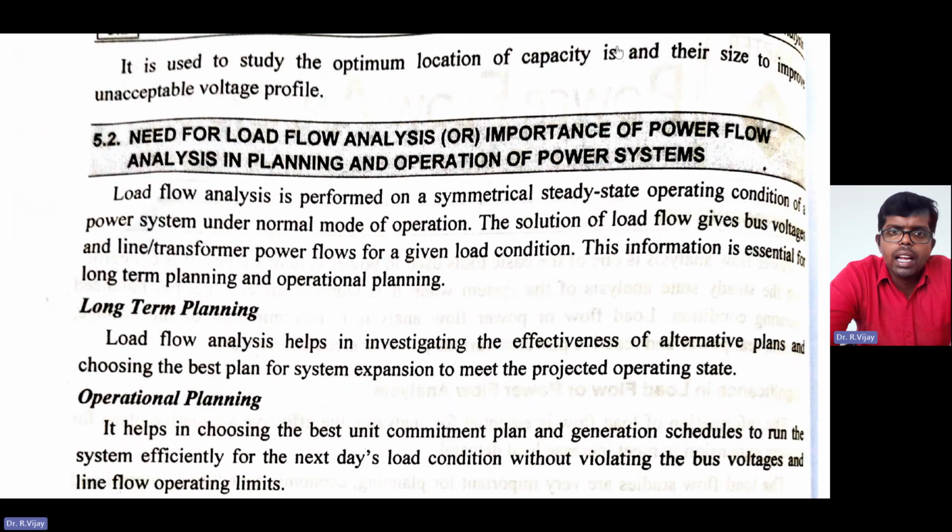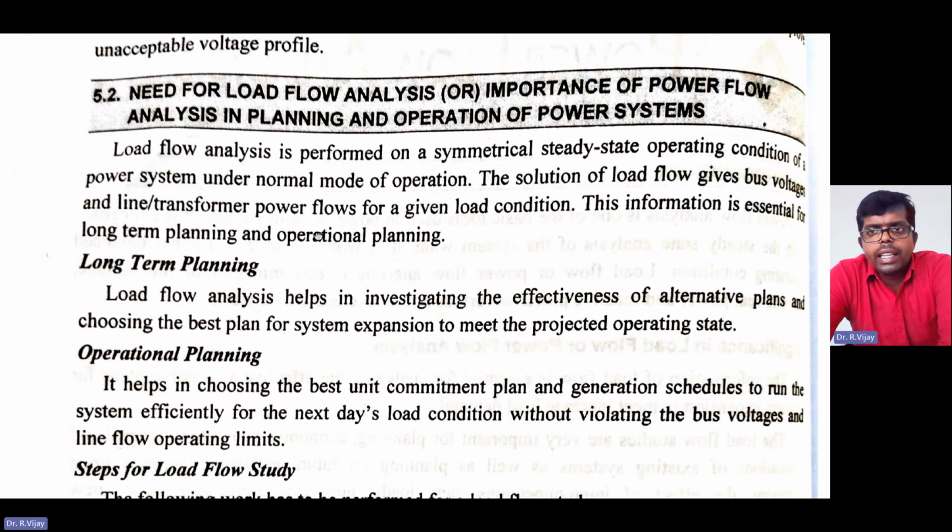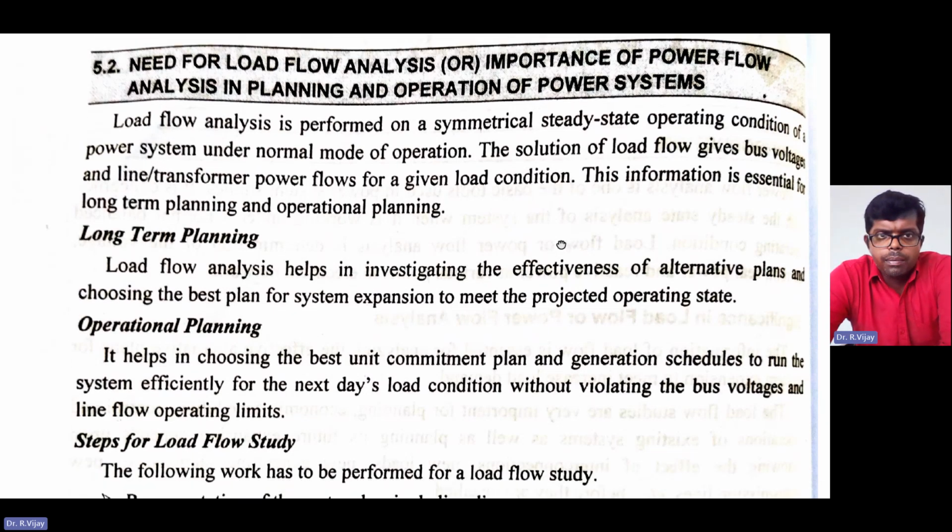Next, coming to the need for load flow analysis, or the importance of load flow analysis in planning and operation of the power system. Load flow analysis is performed under the symmetrical steady state operating condition of the power system, under the normal mode of operation. The solution to load flow gives the bus voltage, line and transformer power flows for a given load condition. This information is essential for long-term planning and operational planning.